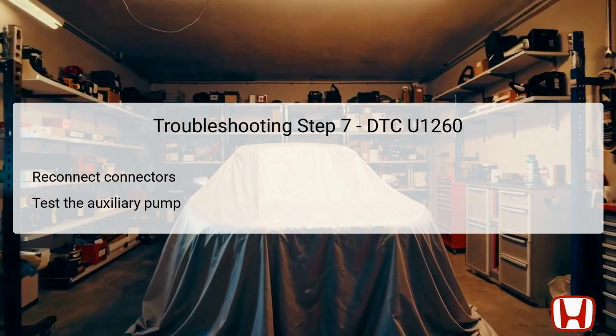However, if the pump fails the test, replacement of the auxiliary transmission fluid pump is indicated as the next appropriate action. The pump is critical for delivering adequate hydraulic pressure for smooth operation, and any malfunction can lead to significant transmission issues. Confirming the pump's status is essential to ensure that the DTC U1260 does not reoccur.